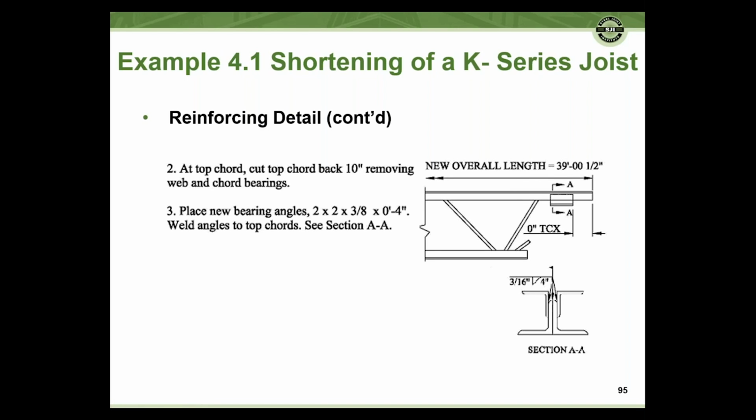You may want to add, and I would recommend, although the detail doesn't show it, just a 1-inch weld at the toes here. The detail doesn't show it, but it's good practice just to add a 1-inch weld in this location. It just keeps these angles from coming out a little bit. It just gives you a little continuity.